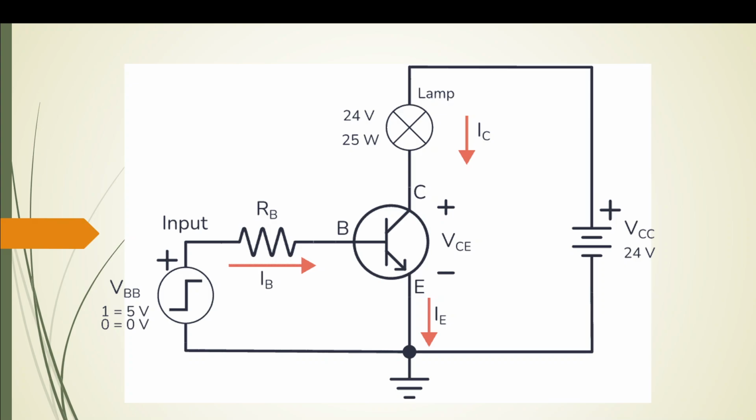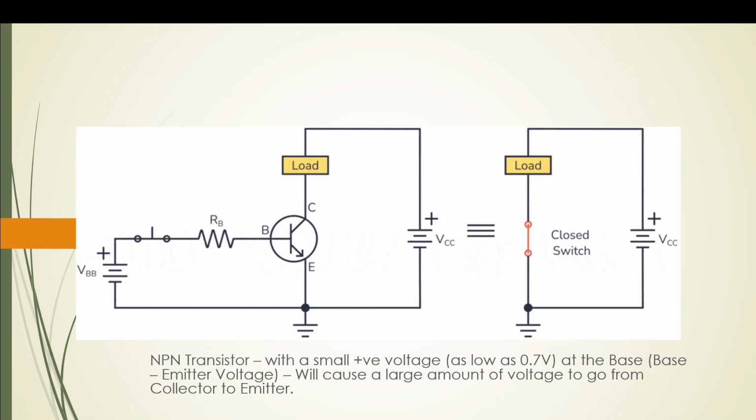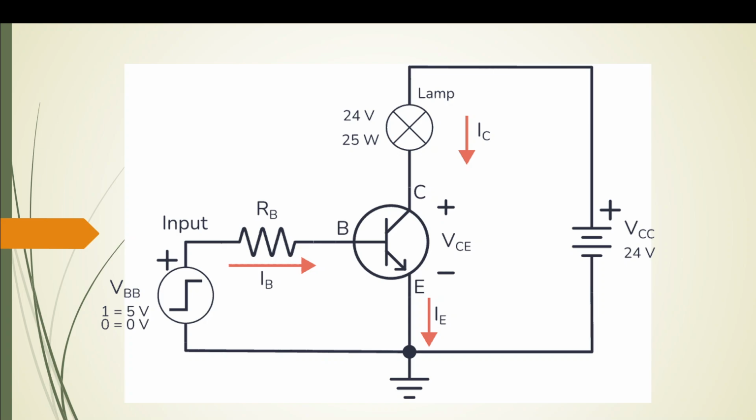This is a similar kind of circuit, but over here we don't use the physical switch. Over here I'm using Arduino to generate a high or a low. On the left hand side, a high, which is a 1, is basically 5 volts, and a 0, which is a low, is 0 volts. So when I pass a high through the resistance to the base, that means I am passing 5 volts to the base.